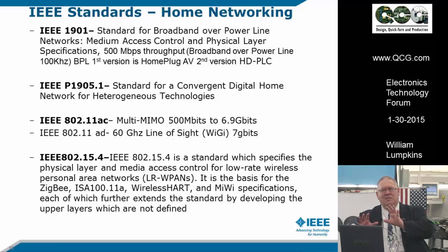But this is interesting because the people that work on these types of technologies don't think about some of the other aspects, which we'll talk about a little bit later, like EMC, the type of noise we're worried about. Normally, a lot of you electrical engineers in the audience, we try to clean up our power as much as possible. When we see 100 kilohertz radiation, we try to eliminate it because we know it's going to cause us EMI, FCC problems later. So we try to get rid of it as much as possible. Now this particular standard is actually trying to use that frequency band on the power to be usable. So now we have to consider how we still use that for Wi-Fi without eliminating it and have extra energy coming out of our product, which might damage us later.